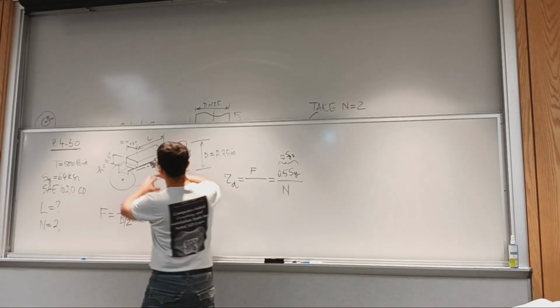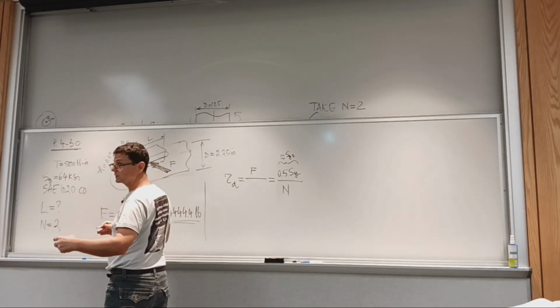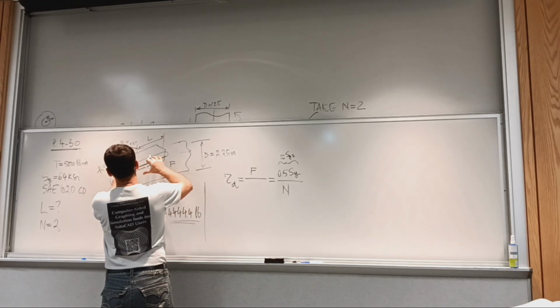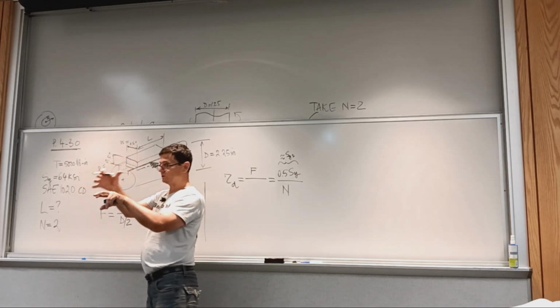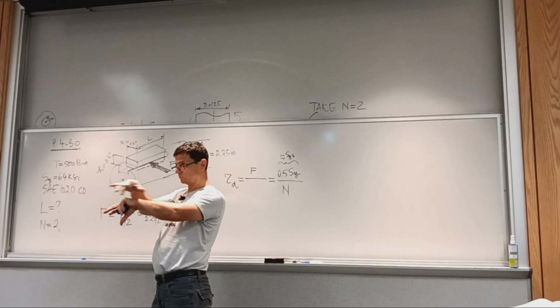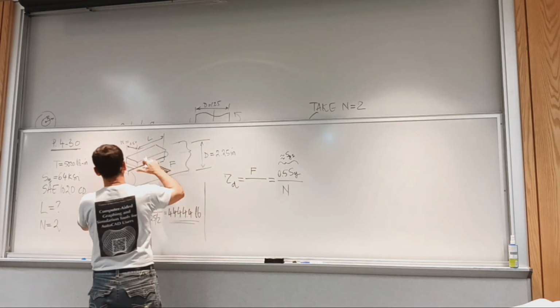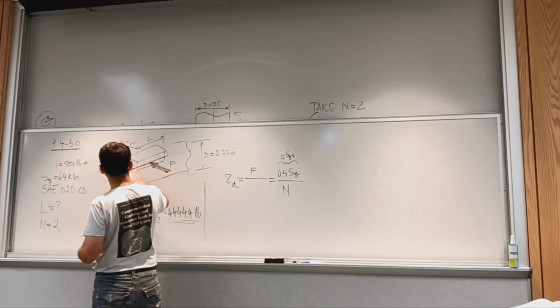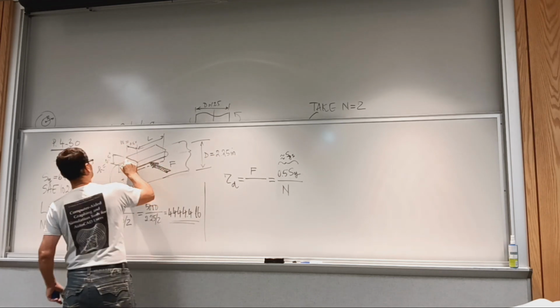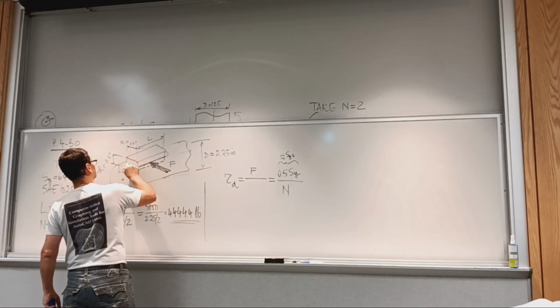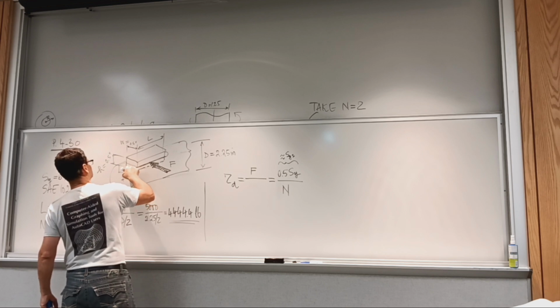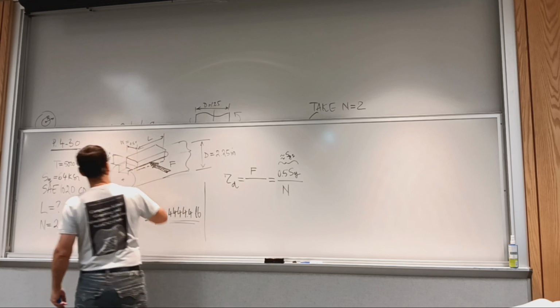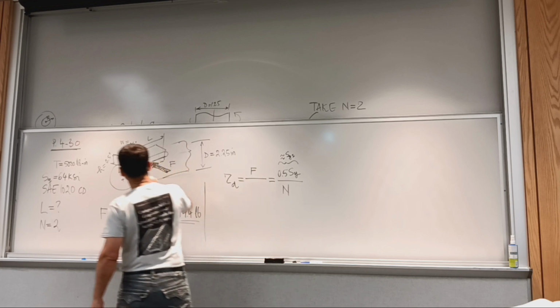Essentially you have the hub and the key, and they tend to rotate relative to each other due to the loading. Look also at the figure in the book. If you imagine the key being very soft material, it would shear. The key sits all the way to the bottom. So what is the shear area?